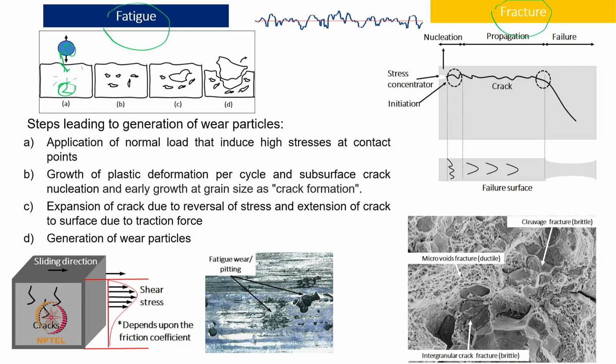That means whatever residual stress is there will again be relieved, and there is a possibility of crack initiation or expansion. Another thing I mentioned here is that if you see, small cracks are available in this case. These are inherent in the material; all materials will have this kind of maybe nano level cracks. When the loading and unloading is sufficient to increase the size of the crack, that increased size is shown over here. Finally, there is merging of 3-4 cracks, maybe 2 cracks get merged and become a big crack.